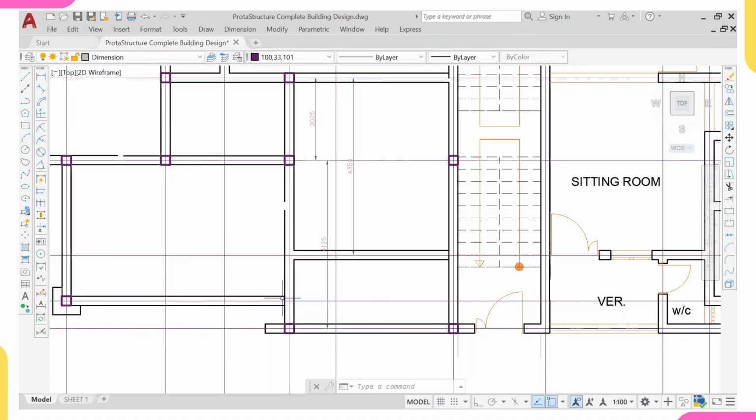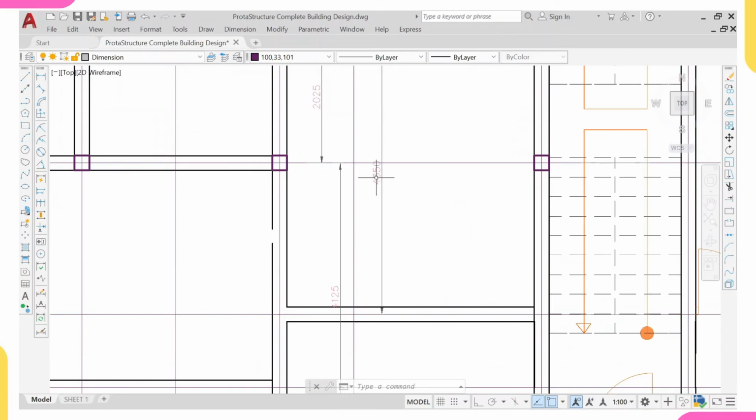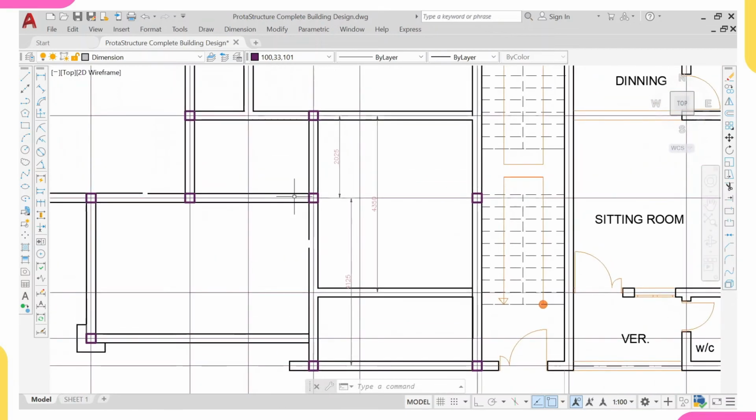So this beam now is a point load to this beam, and this beam is also carrying a point load from this. But if I move this column to this point now, even though the span has increased to 3.25, it will be carrying only 1-point load. So I'll prefer to move this beam to this point because the load on this column will be somehow even. If you leave this like this, the load coming to this beam is too high. It's too much.